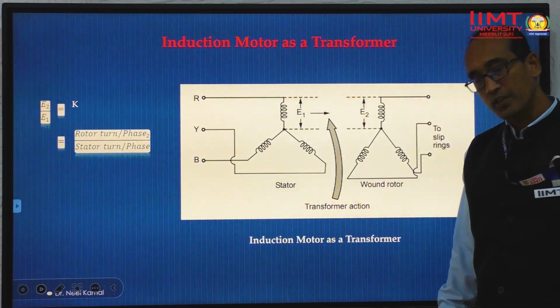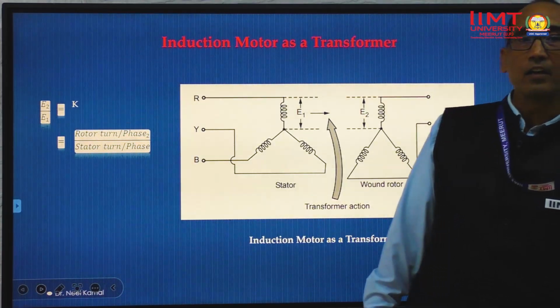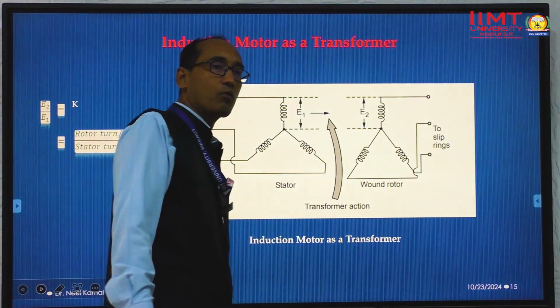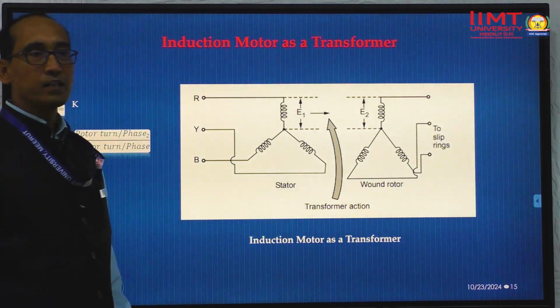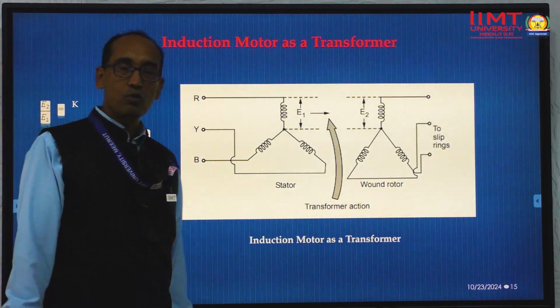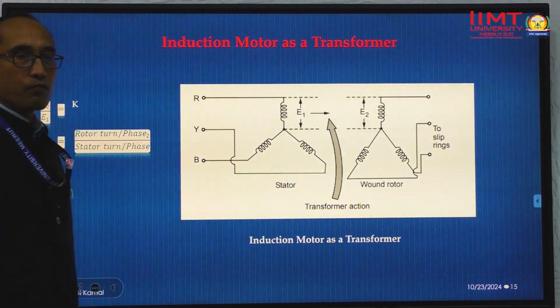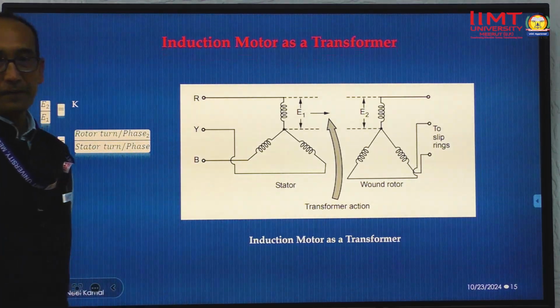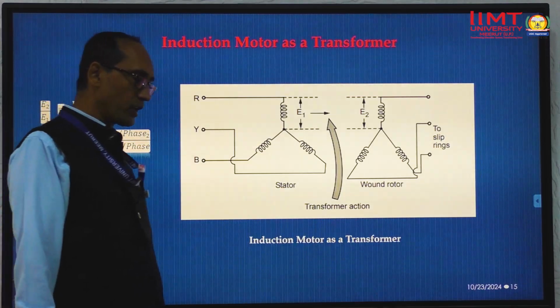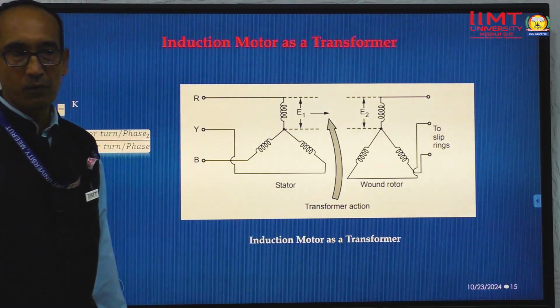But in the case of a three-phase induction motor, on the rotor side, as we have discussed earlier, the rotor has a frequency that is multiplied by the slip. So it will be reduced greatly. We already have the range for the slip, 1 to 4%.